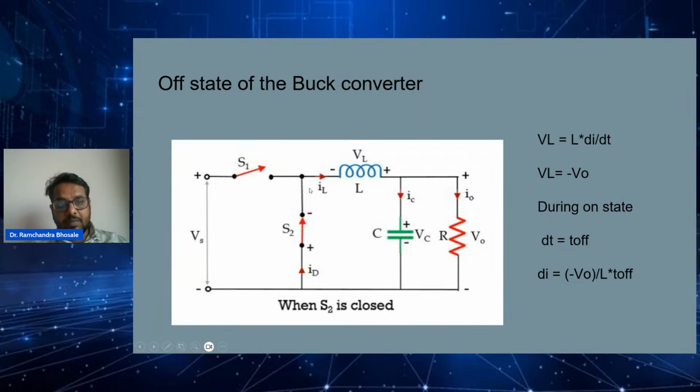But in this case you are generating some on-off voltage across these two points, and there is an LC filter. The LC filter acts to remove the square component from the waveform, and it will give the DC output voltage.